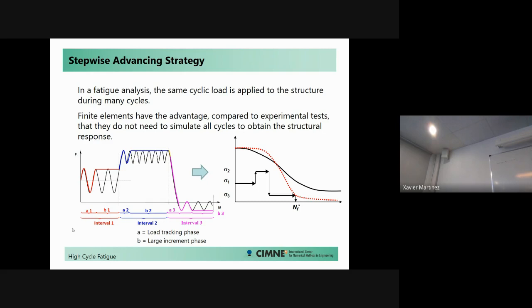And what is the normal general practice when you're doing a fatigue simulation is you set up the simulation inside ANSYS or Abaqus or whatever finite element code you want to use. You run the first cycle of loading with an elastic simulation if you are in high cycle fatigue, with a plastic model if you are in ultra low cycle or low cycle fatigue. And you look at the maximum level of stress or plastic deformation during that first cycle of loading.